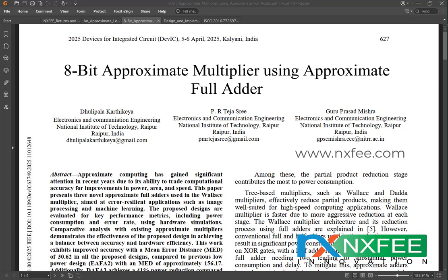This method offers advantages such as lower switching activity and reductions in heat dissipation, but it also faces certain limitations, including error accumulation and the need for efficient alternative structures. Thus, in this work we use reversible gate structures too. The existing reversible approximate full adders have many designs, but they present more error. So this project aims to design error reduction in reversible approximate full adders with a lower cost and